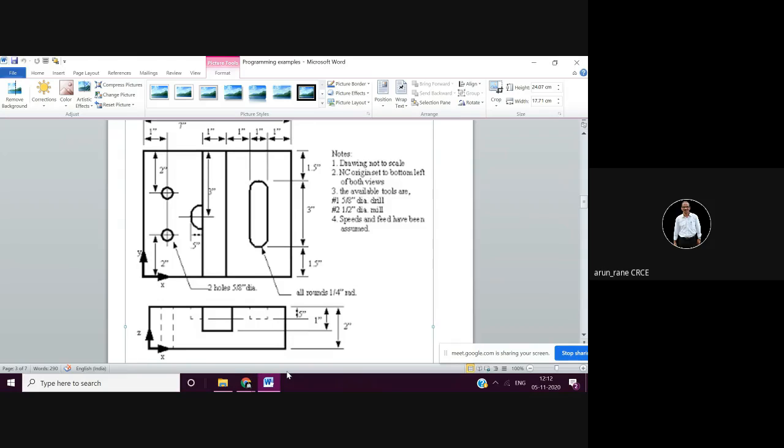Now here, whenever you say plus, the machining is also happening in plus, and only if it is above 2 inch then it is in the air. So that you always have to remember. Now it is always a good practice to have Z0 on the surface, because that gives a clear cut picture: if you are going in negative, Z minus, meaning cutting is happening, then you have to use G01, and if Z is going plus, meaning you are in the air, then use rapid.